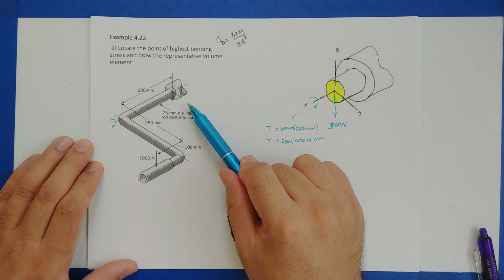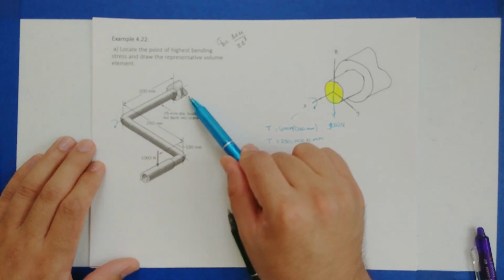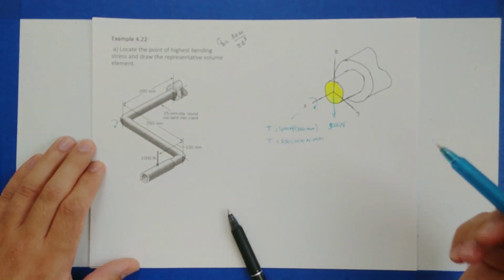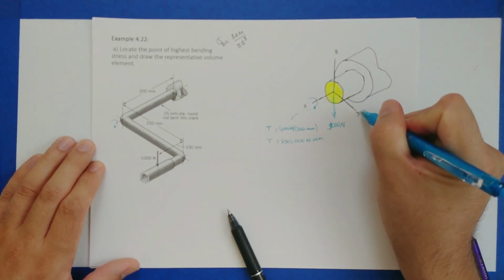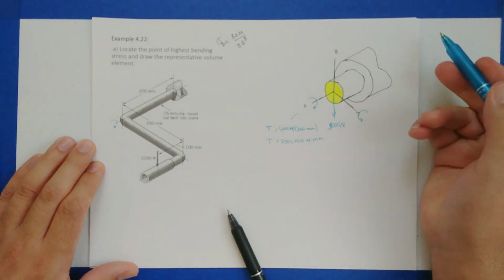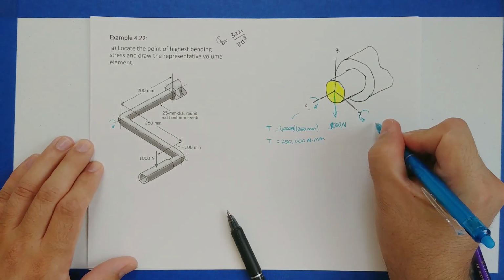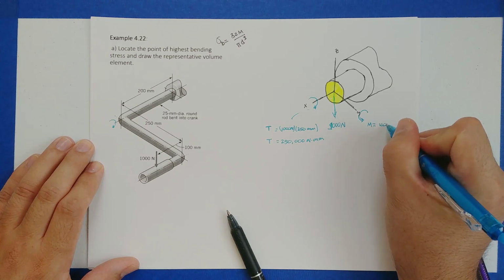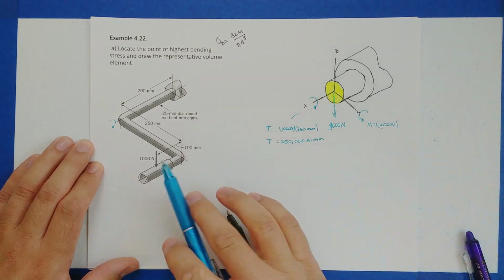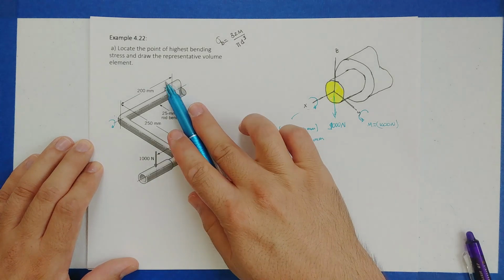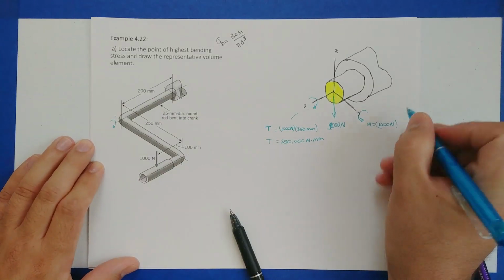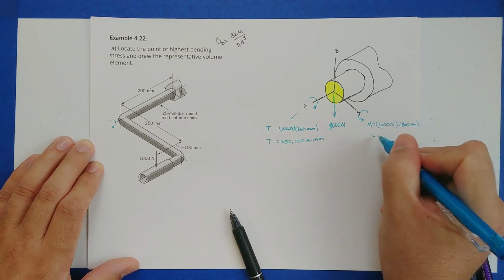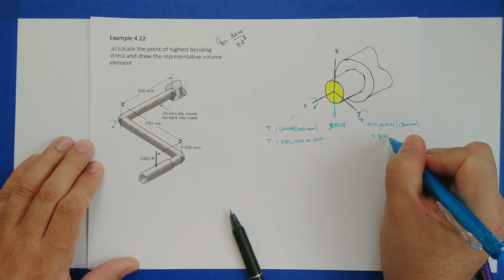Next, because we had to slide this force some distance to get to the y-axis over here, how much was that distance? Well, it's this distance in the x. So we can generate a moment about the y-axis. This is going to be a bending moment of 1,000 newtons times the distance to get to the y-axis. Well, that distance is 200 plus 100, or 300 millimeters, which means I have a bending moment of 300,000